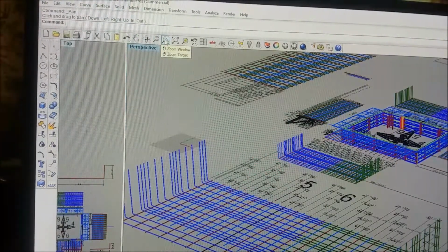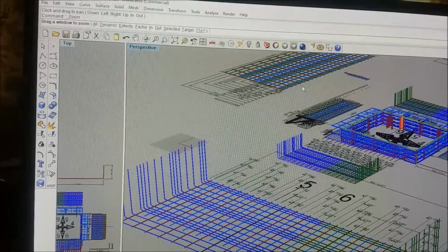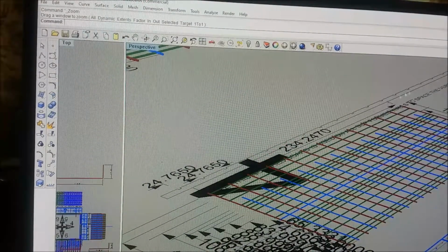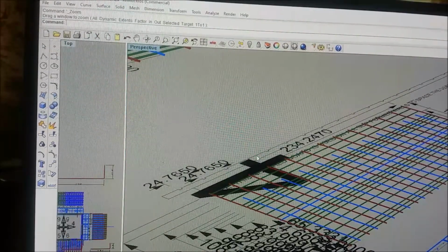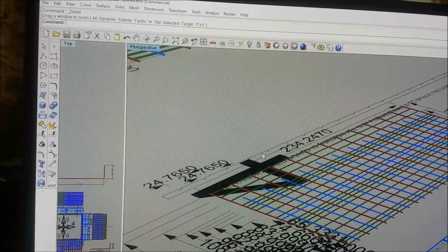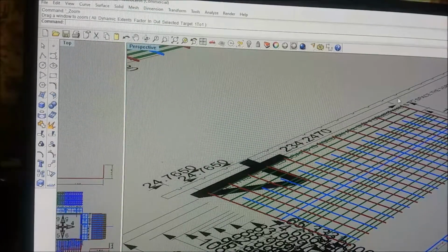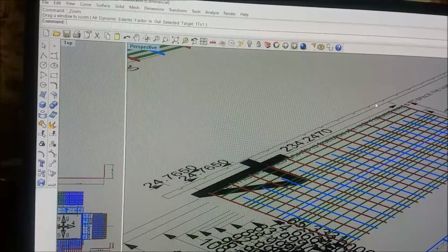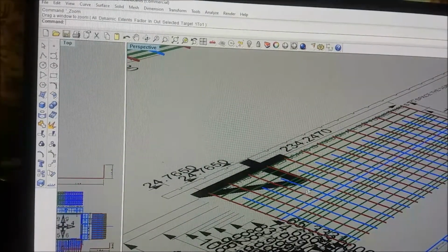What we're going to look at here, good a place as any. Let's just look at this. What you see here is a board running along with the edges nicked out. We call that a notched board. This is how we tie our rebar. We have 2 boards sitting on a floor someplace, or out in the grass, whatever you're doing. And you drop a bar in each one of these notches. And you have 1 or 2 more of these, depending how long it is. For 10 feet, you have 2, or 12 feet. And for 18 foot 6, you'd have 3 if you're a full length bar. And that spaces them exactly the way you want them.